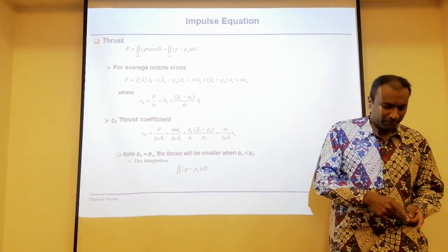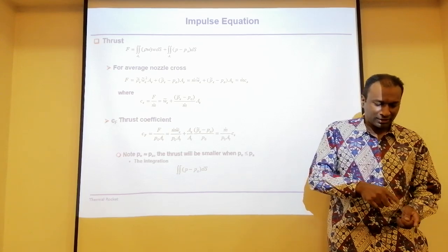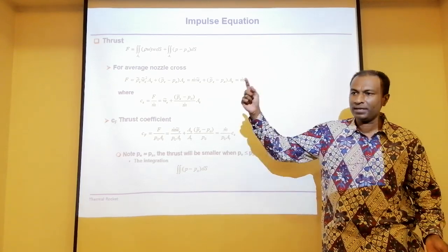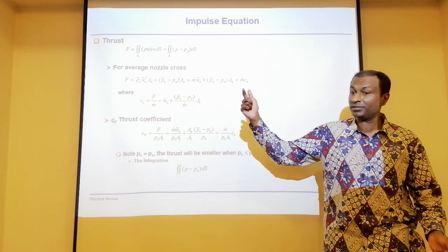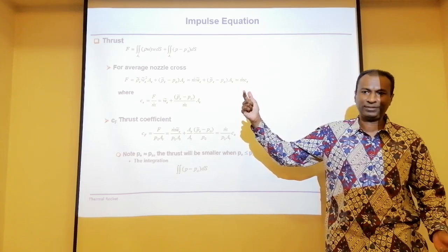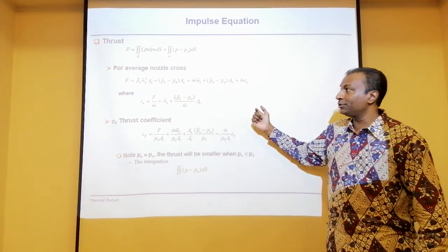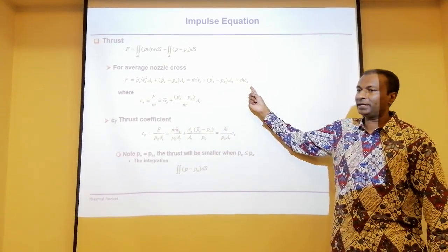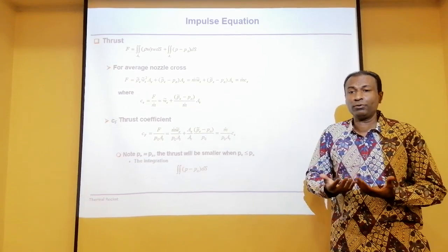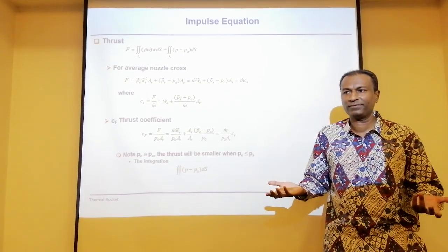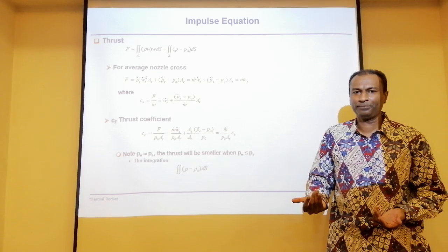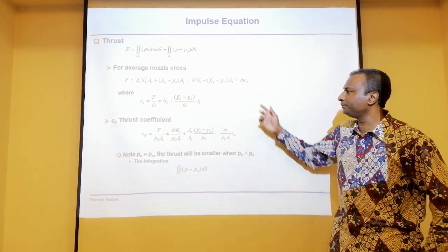Now, if you look at the trajectory from point A to point B, atmospheric pressure, you can't control it. It changes. Therefore, this keeps on changing. Which means that the effective exit velocity will actually be lower, in fact. Okay, will be much lower.